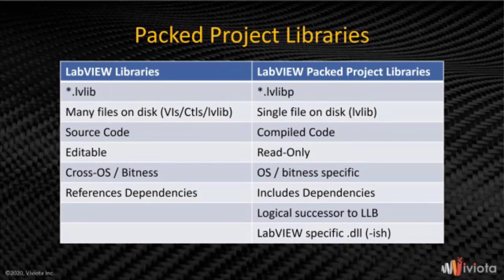Paul asked, what about LabVIEW versions? That's a good question. So prior to, I think, LabVIEW 2018, you had to compile it for each LabVIEW version. From 2018 on, it might have been 2017, there's now the option to make packed project libraries forward compatible.